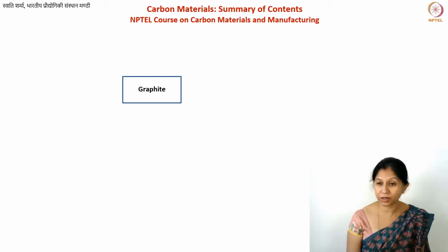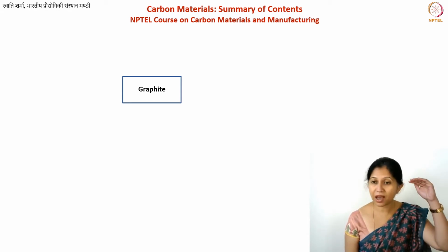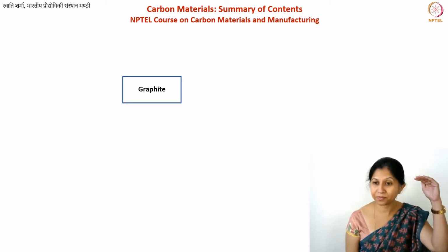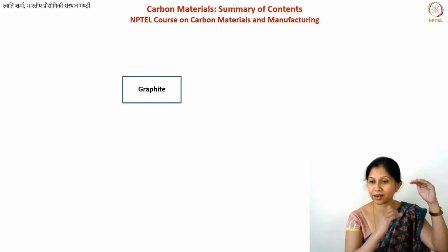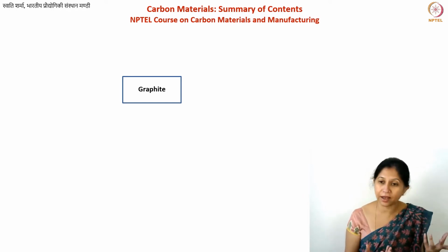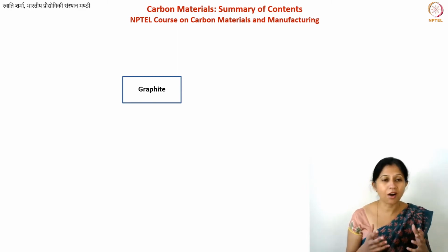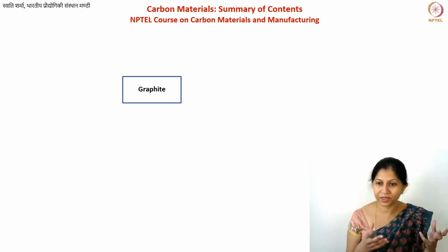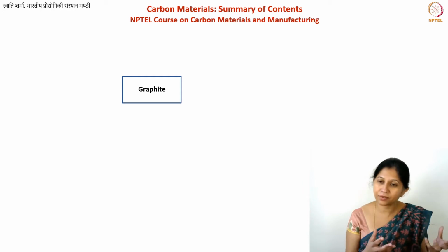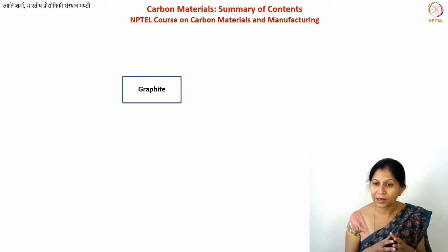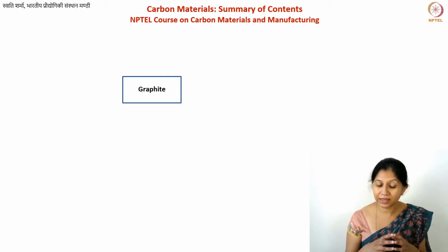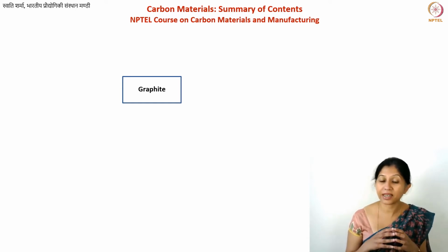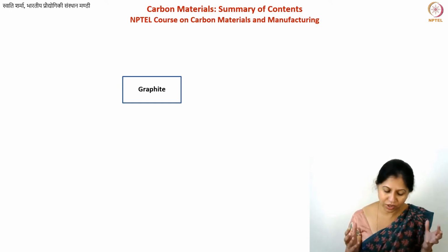When we were learning about a certain disordered carbon material, I told you that our reference standard is graphite. And then we are trying to get there, or even when we are not trying to get there, or we know that we are making a non-graphitizing type carbon, still we are always comparing the properties, say crystallinity, with that of a graphite crystal. So understanding the graphite crystal structure and some of the fundamental properties of graphite is essential when you're starting,